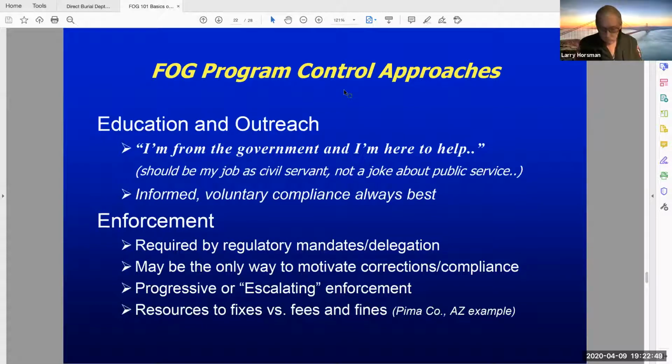But it is a big deal, and I know restaurants are common. I think when I did some work on Khan's Cave, it had previously been a Chinese restaurant, and they didn't have an interceptor in there. And then when they switched over to the new restaurant, they had to put a 1,500 gallon interceptor out in the parking lot. So normally, if you're going to put a gravity interceptor, that should be outside in the parking lot so they don't have to go inside the building to work on them. Wow. That must have cost quite a bit.